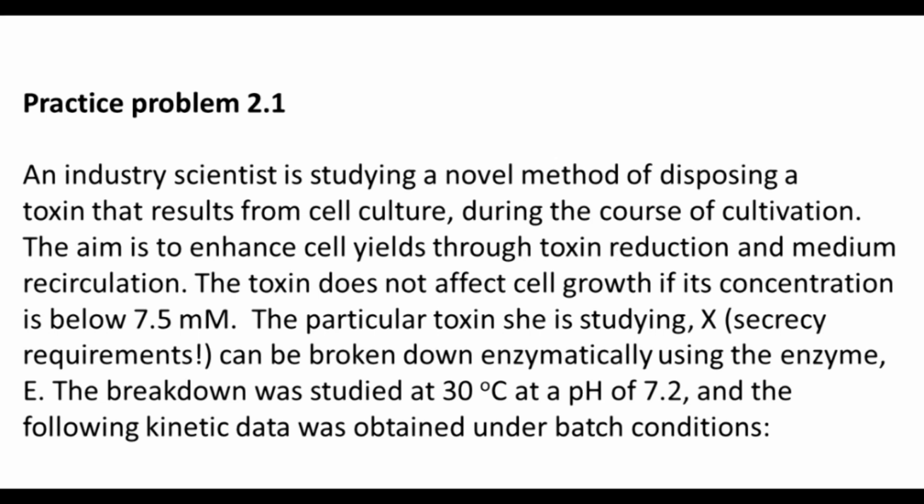We said that we need the kinetics of the enzyme reaction. We went through the derivation of the Michaelis-Menten equation, which has two parameters, Vm and Km. In form, it is very similar to the Monod equation, which describes the variation of growth rate with substrate concentration. Here it's the variation of enzyme volumetric rate with the substrate concentration.